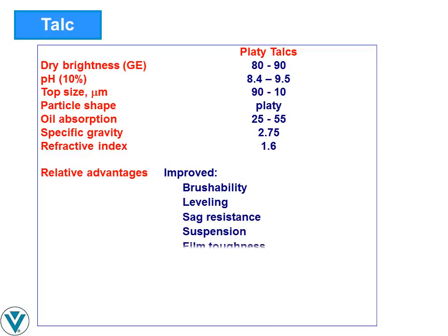Platy talc improves the toughness and general durability of paint films. The talc plates tend to align with the coating's flow so that they are parallel to the substrate in the dry film. This creates a physical barrier to the transmission of moisture, thereby improving water and humidity resistance. This impermeability can aid, however, in the formation of blisters as any moisture or gases leave the substrate.